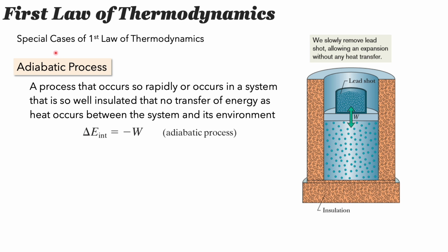Now, the first special case of the first law of thermodynamics is an adiabatic process. In an adiabatic process, we change the state of a system without any heat transfer. So, the process occurs so rapidly, or occurs in a system that is so well insulated, that no transfer of energy as heat occurs between the system and its environment.